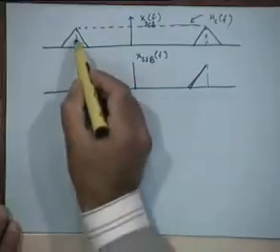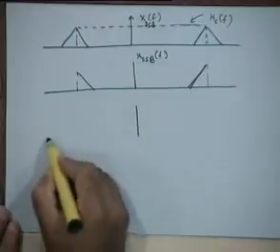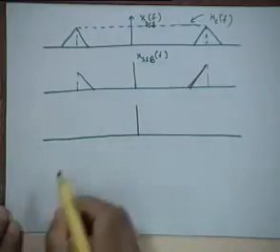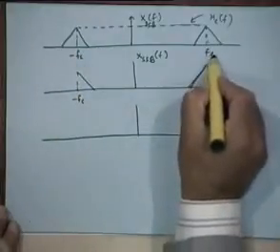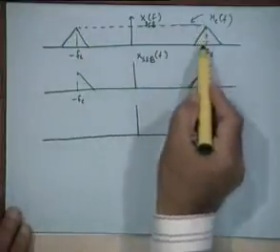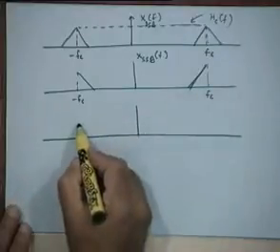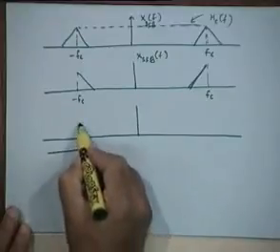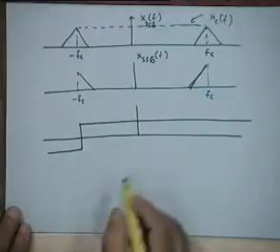So now let's look at this ideal low pass filter. I can represent this ideal low pass filter as the sum of two signum functions. This is minus FC, this is plus FC. Can you see that? I can represent this rectangular function which specifies the ideal low pass filter as the sum of a function like that.